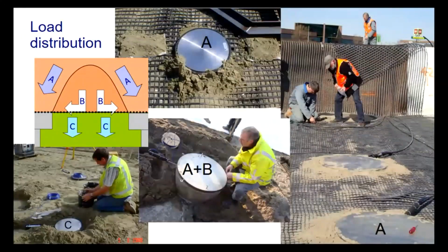This is in the field. Here we have 85 centimeter wide pile caps and a total pressure cell of exactly the same size on top of that. That weighs 200 kilos, the pressure cell itself. They work really nice, already 12 years.